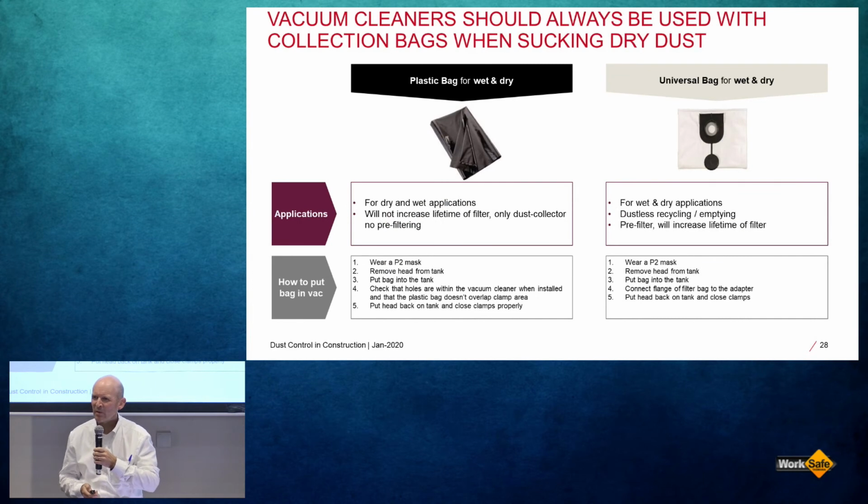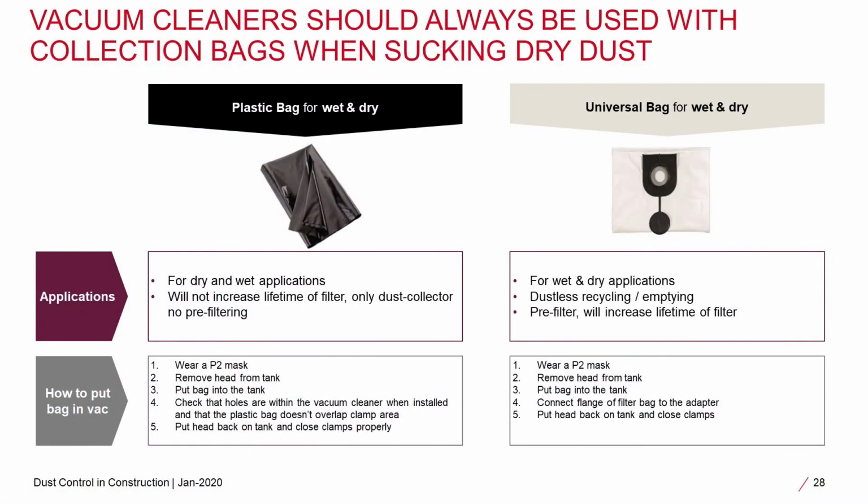Bagging dust is really important, because when we've looked at reports of occupational hygienic assessments that have been done on site, most of the highest readings are from labourers and cleaners emptying vacuum cleaners into skips. So they take a vacuum cleaner without a bag, upend it, and get covered in a huge plume of dust. So it's real important to bag the dust. It's the simple things, isn't it, that trip us up.